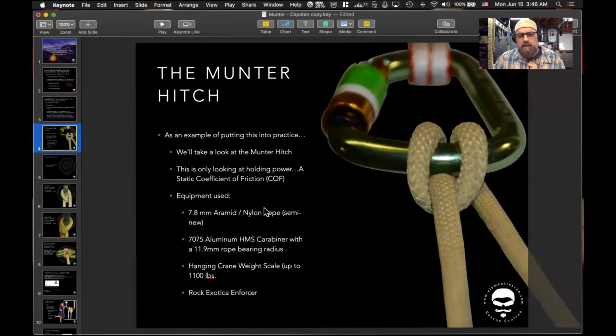With this, we tell you this information because you'll see that one of the downsides that people don't understand really with the capstan or the belt friction equation is if I change my rope, not even diameter, just the manufacturer or the materials that it's manufactured out of, it will change my answer.